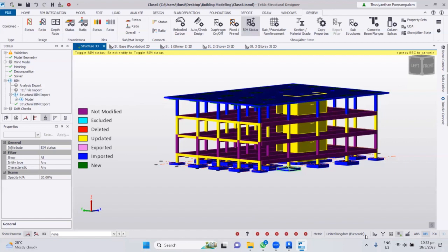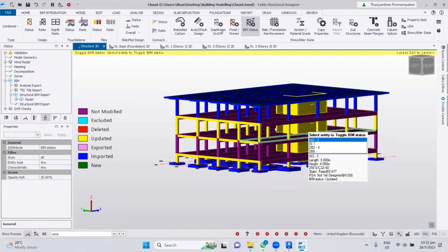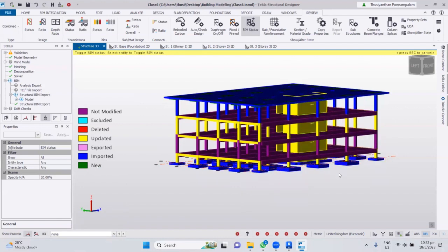It's not just a new model; you can update the existing model. If you create a new model, the problem is loading, because Revit does not keep the loading information. If you import as a new file, you don't see the loadings and you have to create new loadings. But if you import as an existing model, that means you update the model, you keep all the loadings. So just update only the changes, don't touch other areas, and then you can keep your loading.